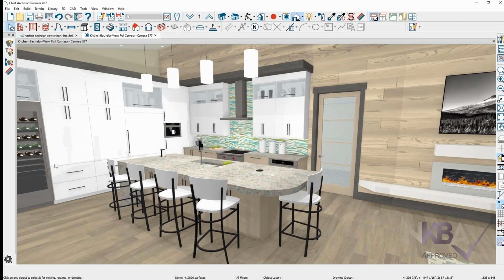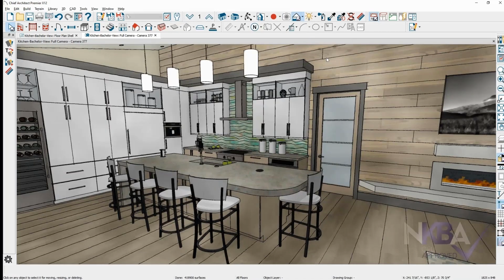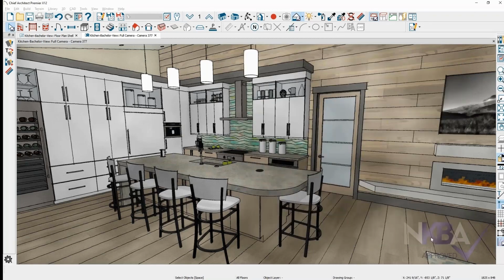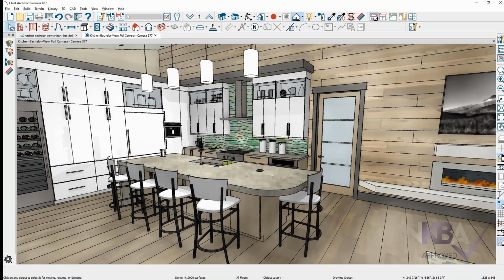Okay, a few things. Obviously, make sure that your lighting is turned on. Let me just switch this back to the watercolor view here real quickly. In this case, I feel like this is a little bit dark, and you saw me turn on more lights. The easiest way would be to crank up your lights to 50 or something if it's a simple design.